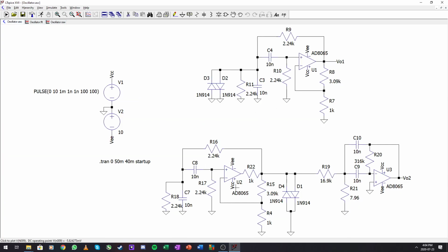And there's how you take a bandpass filter and convert it into an oscillator. And if you want pure outputs, just put it through another bandpass filter like that.